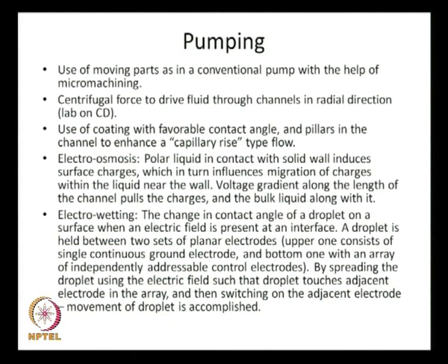Centrifugal force to drive fluid through channels in the radial direction, which is referred to as lab on CD. This is used in certain industry. So, these I have discussed here. The third one is use of coating with favorable contact angle and pillars in the channel to enhance capillary rise type flow. So, in a channel you can have favorable contact angle, as I said, capillary rise of water in a glass capillary.